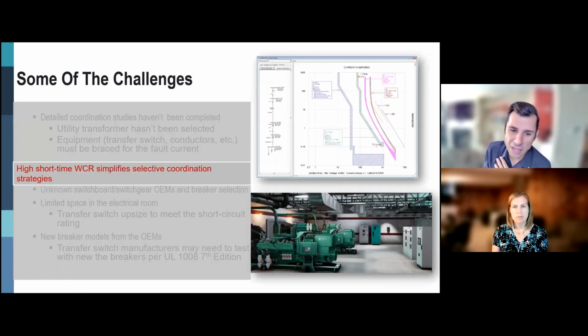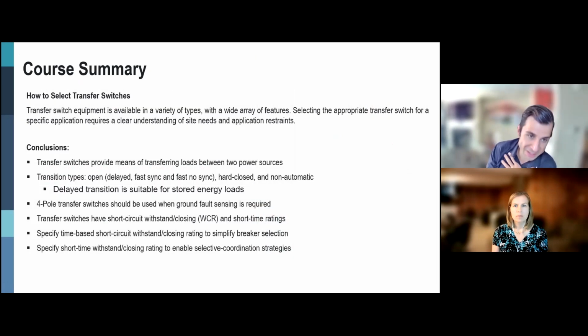If we go back to the challenges that you have, the high short time WCR also helps you in selective coordination strategies. And this takes me to the last slide, which is how to select a transfer switch, and the summary. I hope you enjoyed the course and I hope you learned something. I know it was a lot of information to pack, but transfer switches provide a means for transferring loads between power sources. Four-pole transfer switches should be used when you need ground fault sensing, if ground fault protection is required. Transfer switches have short circuit withstand and closing ratings and short time ratings.